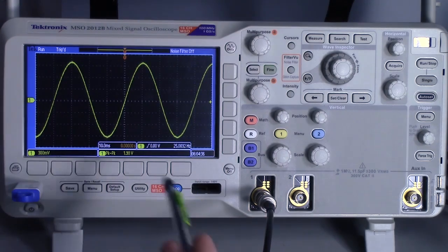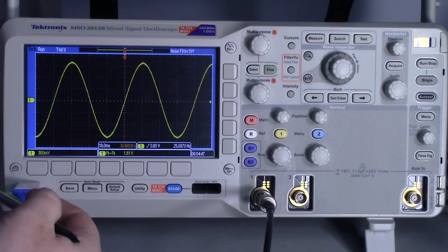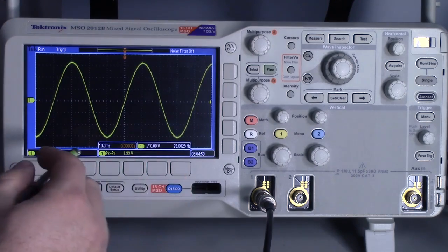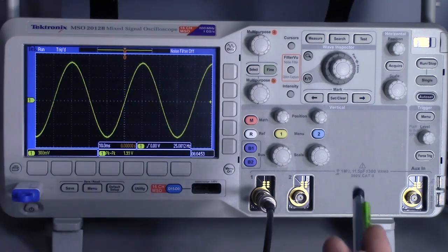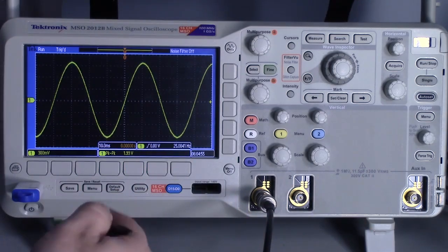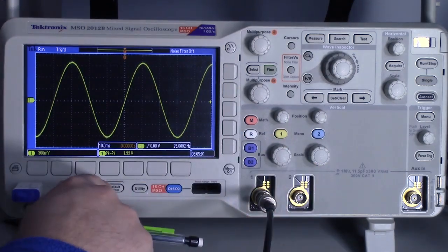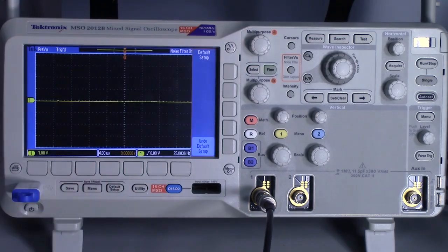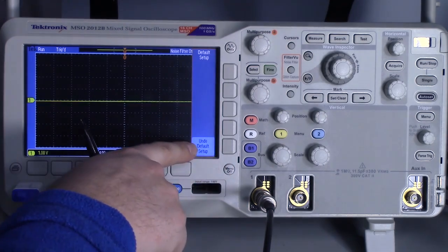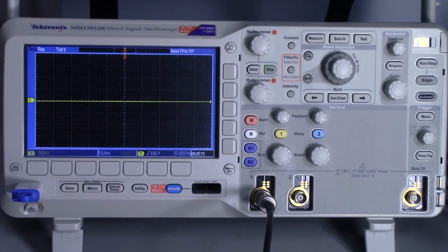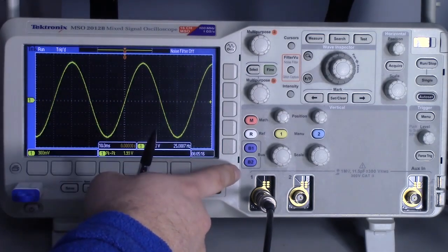Now, if you're using your own oscilloscope and you know what you were doing last time, you probably can skip this step. But in labs, I always recommend for students when they first come in, they turn it on and hit the default setup. A lot of times the people before will have all kinds of various settings that the oscilloscope will retain, and so when you go to plug it in, it looks like it does all kinds of weird stuff. So I always recommend you press the default setup. All it does is set it to a default. So we'll just click that. You can always undo the default, so if you accidentally hit that, you can just go back; it's basically an undo button.